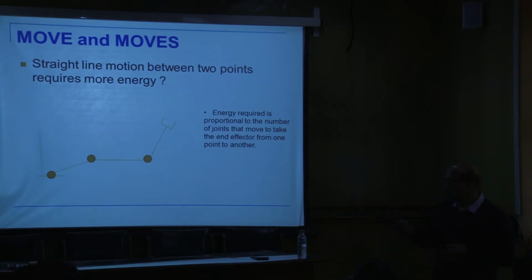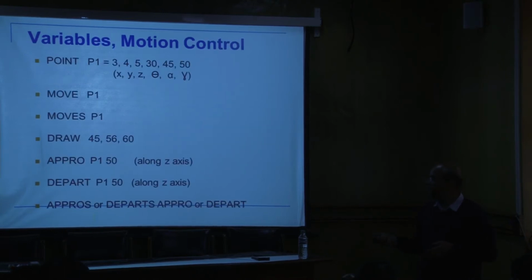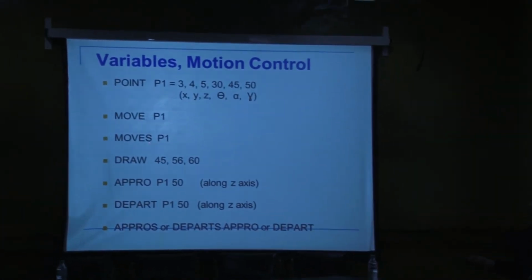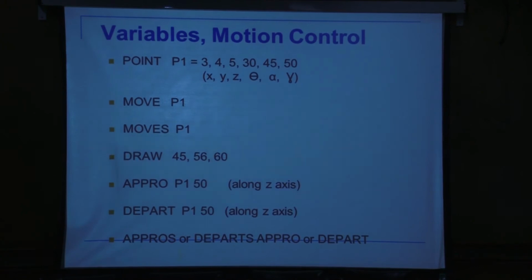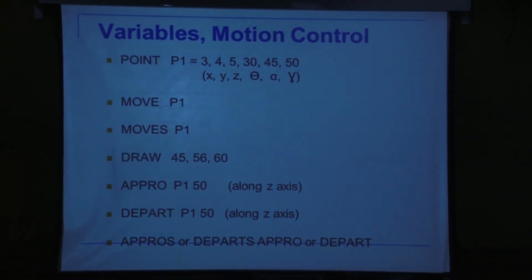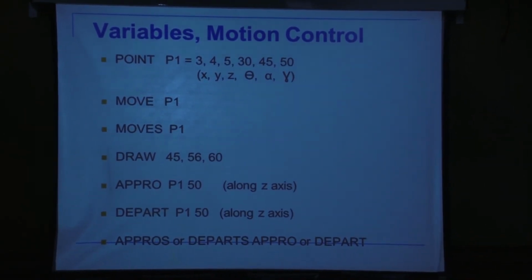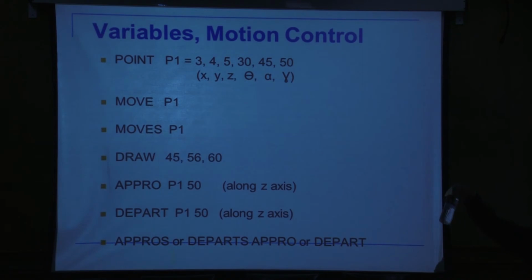So if you want the robot to actually follow a straight line, then you have to use this command. For assembly, this is used, just for moving in space. Again, for picking up an object, for example, when we pick up an object, we always go like this, and we catch it and we go like that. So this motion is always straight. Unlike a human who normally goes from the side, a robot goes from the top, because the chances of hitting something are much lower there.